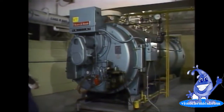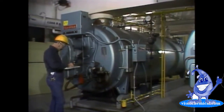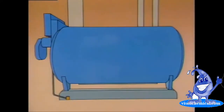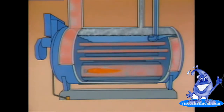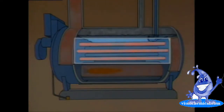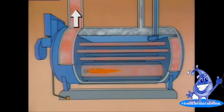Basically, fire tube boilers route hot combustion gases through metal tubes. The tubes run through a shell filled with water. Fire tube boilers vary in design, but most operate under similar principles. The combustion area for this one is here. A group of horizontal fire tubes routes combustion gases through the boiler. There's also an outlet for the gases, a feed water line, and a steam outlet line.